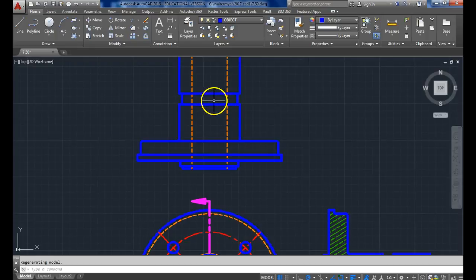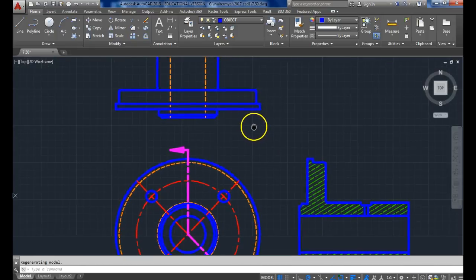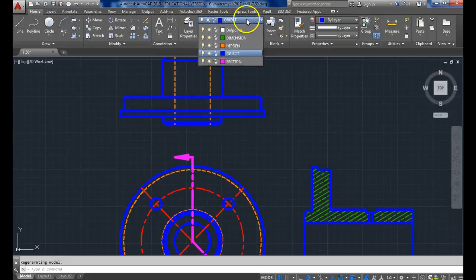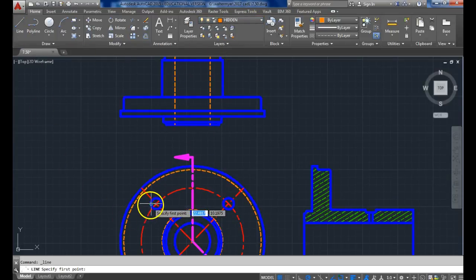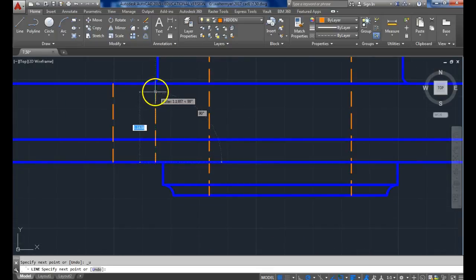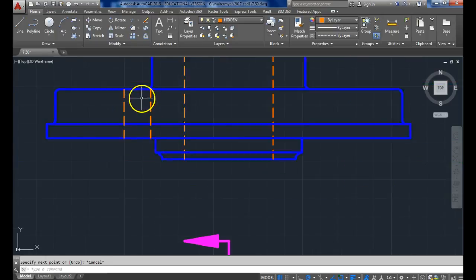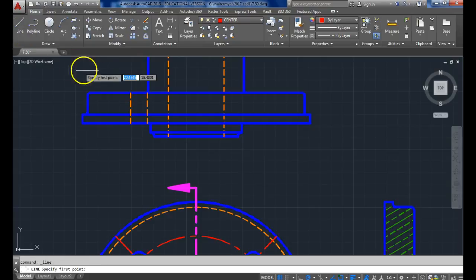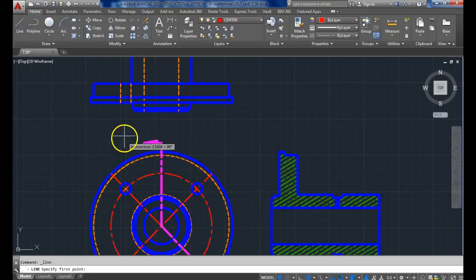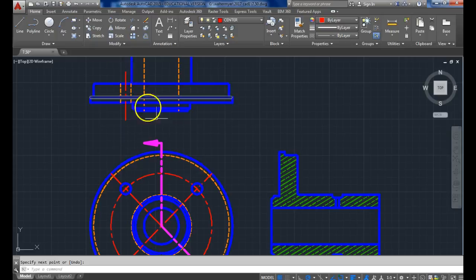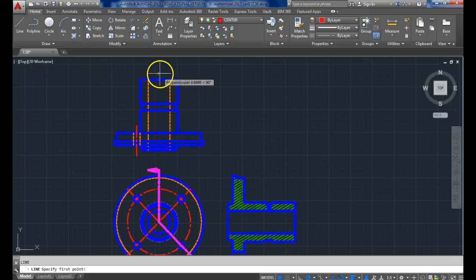Alright, now, a couple things to finish this one up. The holes on the outside here, I bring hidden lines up, bring it from the side, there's one side, bring it from the other. It went on an angle. Straight up. There we go. We add in a center line through the center point. Let me add a center line all the way through the top view.